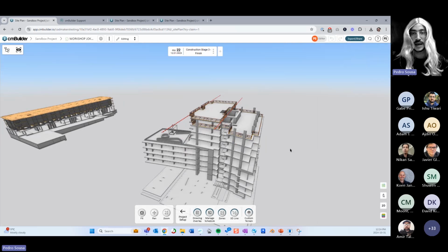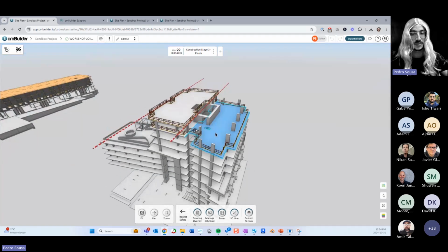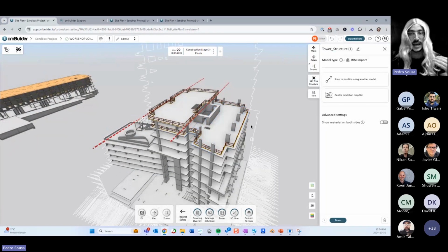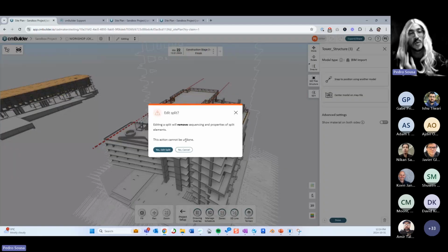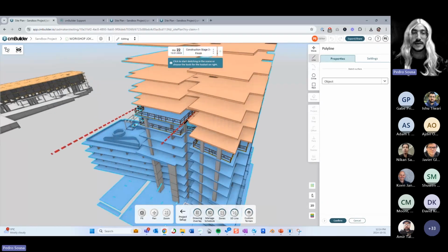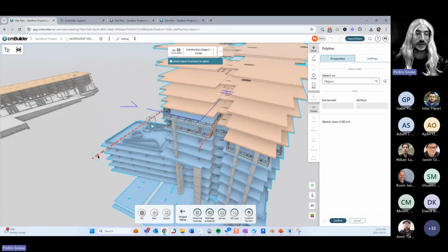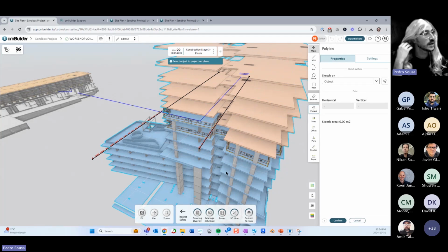And then if I update this model, the next time that I create a split for this model, instead of drawing the lines all over again, you can always take this, and whenever you're creating a line, you can simply do the same thing by projecting the shape of the template. So you have those lines created for you automatically. Okay, so you're going to need to use the tool again, but instead of drawing everything from scratch, you can simply use these templates to slice them again.